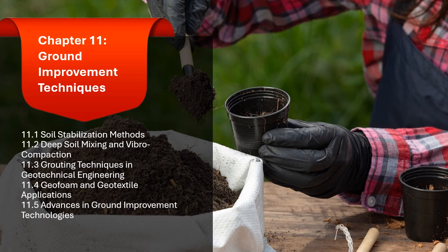High-strength geocells. Recent developments in high-strength polymer materials have made geocells more durable and capable of withstanding heavy loads, increasing their use in a wide range of ground improvement applications. Geocell-enhanced pavement systems. Geocells are being integrated into pavement systems to improve load distribution and prevent cracking, especially in areas with poor soil conditions.